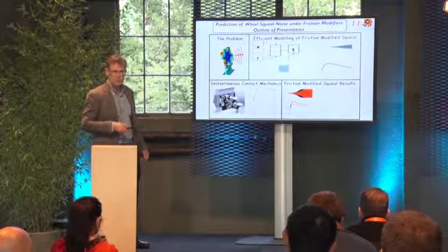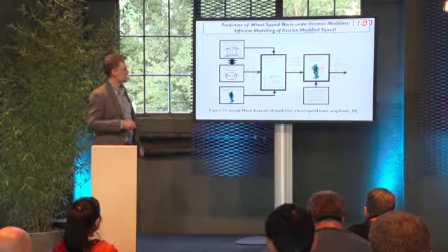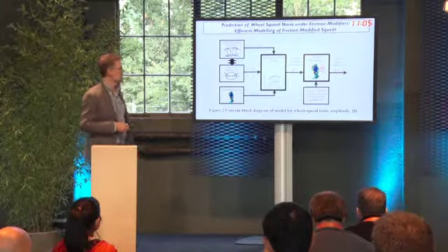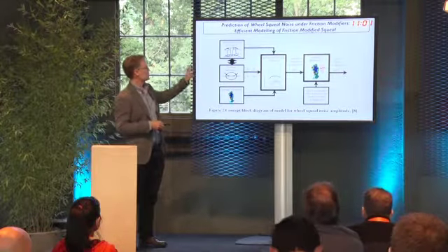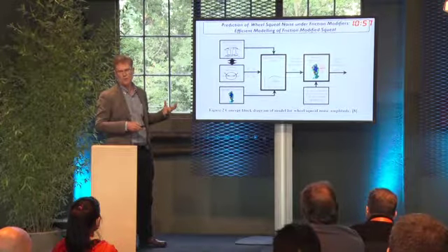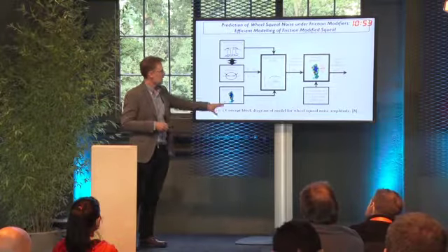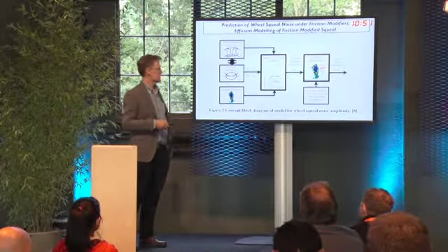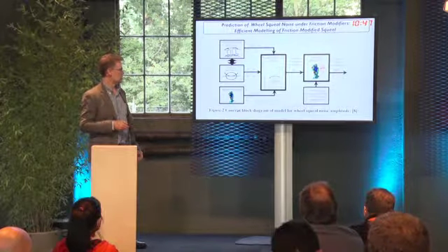So the efficient modelling we've developed to predict wheel squeal is based on this concept diagram shown here, where we have the contact mechanics interacting with the vehicle curving mechanics. We've identified some critical parameters associated with that interaction, and it excites a modal dynamic of the wheel.